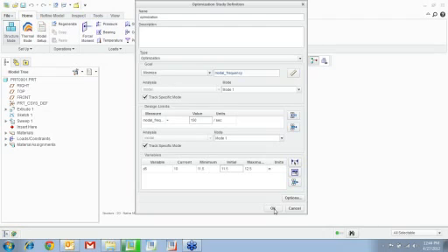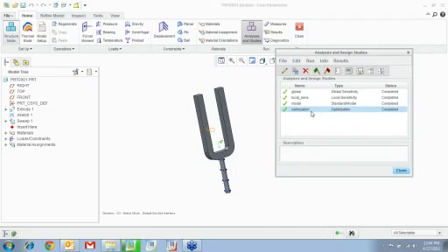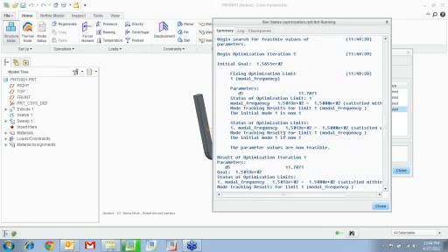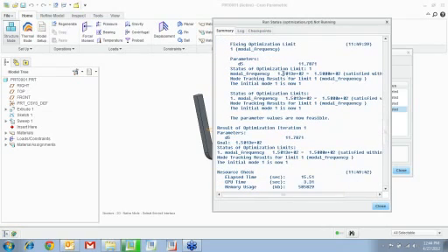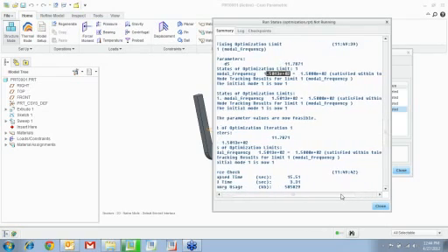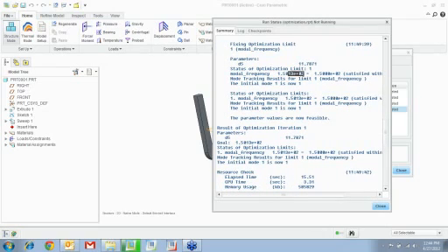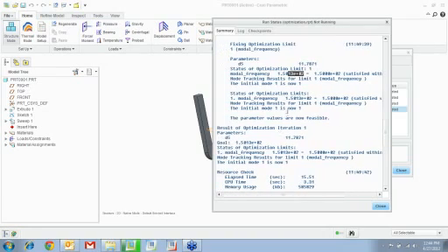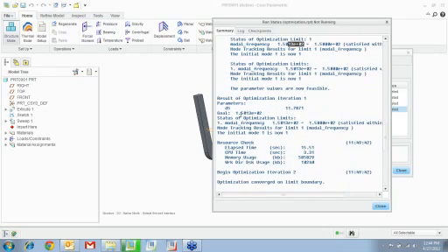All right. So you go ahead, say okay, run an optimization, and you can see the result. In an optimization, you see real quick, it tells you that this is the value that it found, and notice that it is satisfied within the allowable tolerance, which is 150.13, right? It tells you it's reaching that value at 11.78.